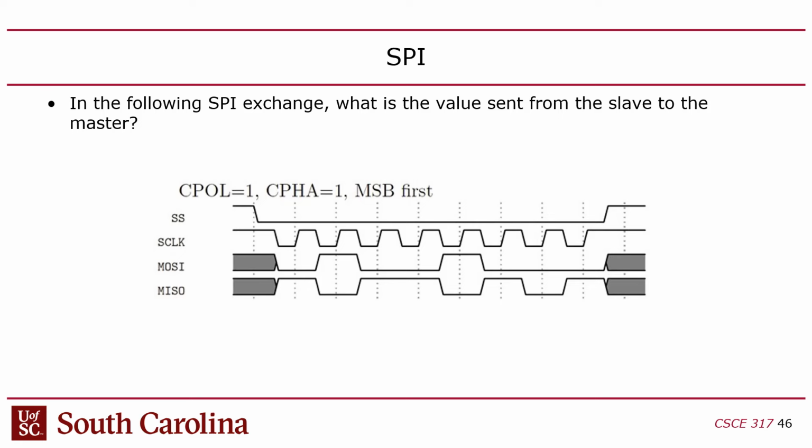Well, hold on one second. I want to add something to that. So if we get this wrong, though, right? Let's say the slave is set up for CPHA 0, and the master is using CPHA 1, right? What happens in that case? What would happen? Well, the slave would read on the first edge, right? Which is a falling edge, and then every falling edge, well, for the next, in this case, 8 falling edges, right? Because there's 8 bits. What would happen if it did that?